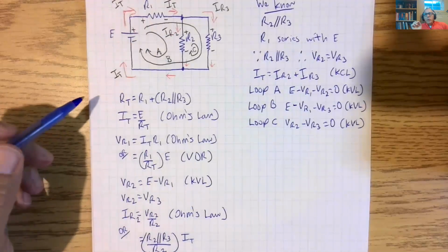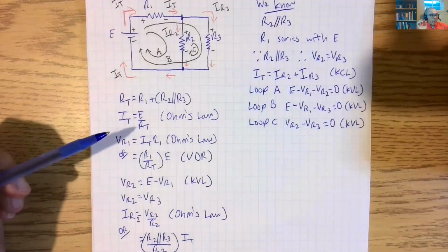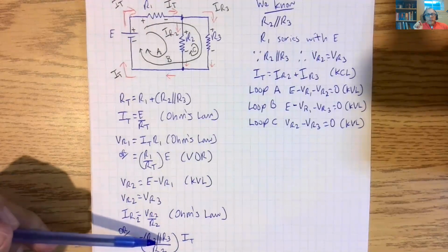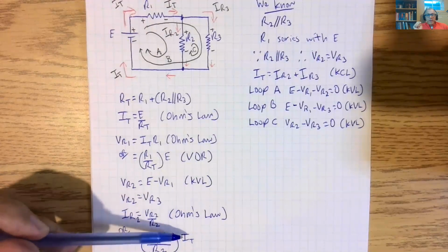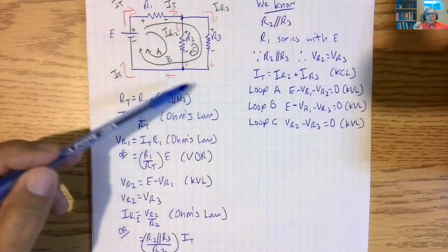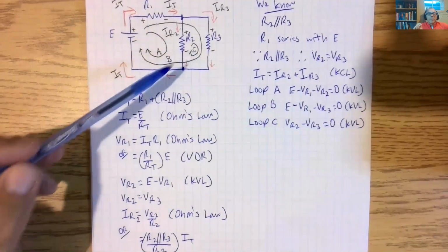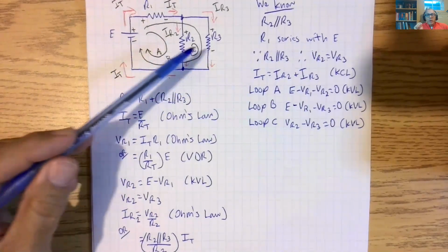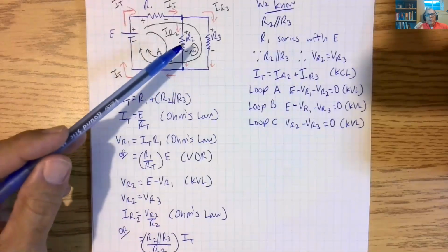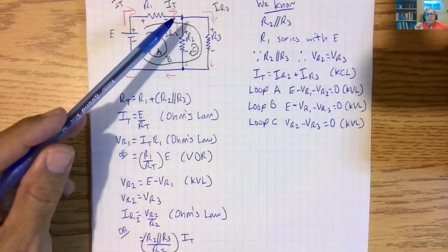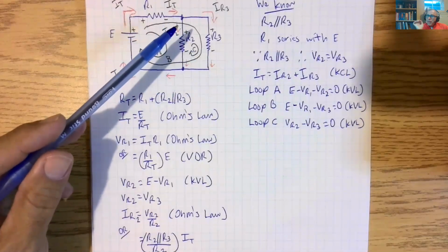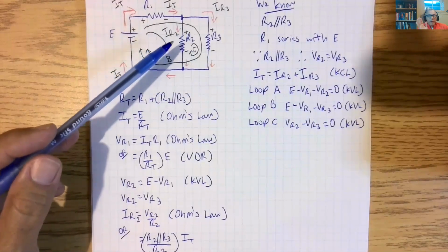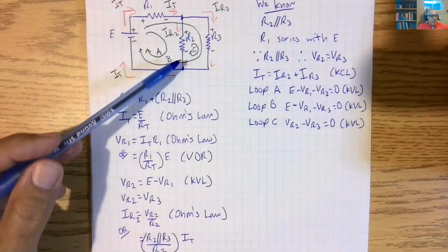Okay, so if you recall, when we're doing parallel circuits, just straight up, we were saying that the current divider rule is RT over that resistor times IT. But in this case, because this is our only parallel part of the circuit, we don't say RT because RT is all this, but we do say the total resistance of this parallel network divided by the resistor we're looking for times the current coming in. Okay, so it's something very important to remember, and we're going to keep beating on that over the next three examples.